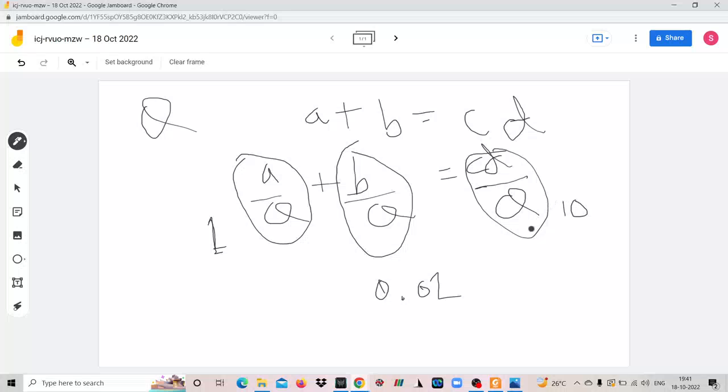So it gives you an idea of which terms of this equation have more relative significance. From this we can see that the relative significance of the term b is less in comparison to a and cd, and the significance of the term c into d is the highest, because it is higher in value. This analysis is the order of magnitude analysis, and this is another reason why we non-dimensionalize the governing equations. It gives you an idea of which terms are more significant.